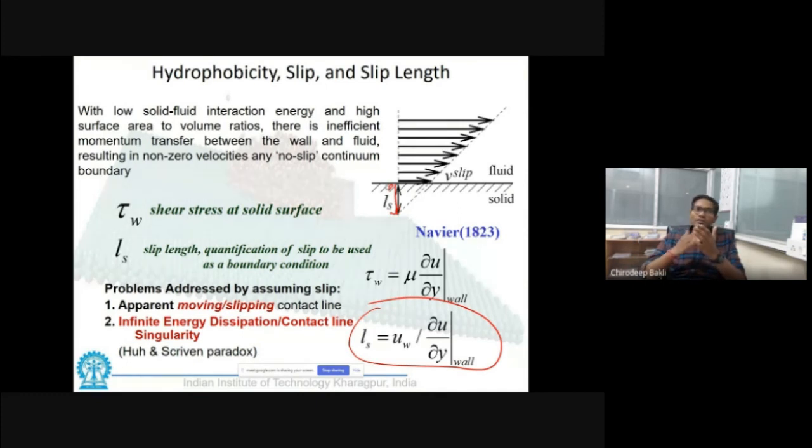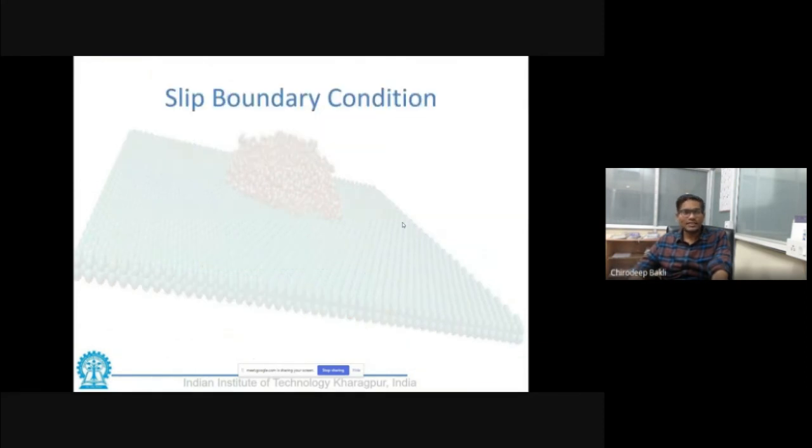Now, this property of slip, fluid layer sliding, is connected to hydrophobicity. A non-wettable surface would not allow wetting of the surface and would be conducive to slip. A wettable surface has capillarity but doesn't allow slip. So this is a concept that has been treated as mutually exclusive in history, and via molecular dynamics simulation, we try to propose a surface where these two concepts are combined.